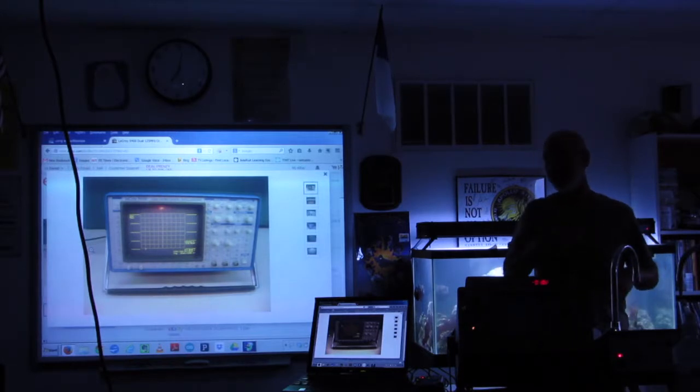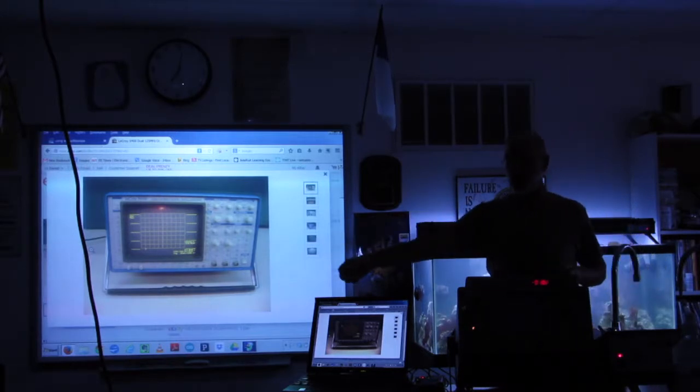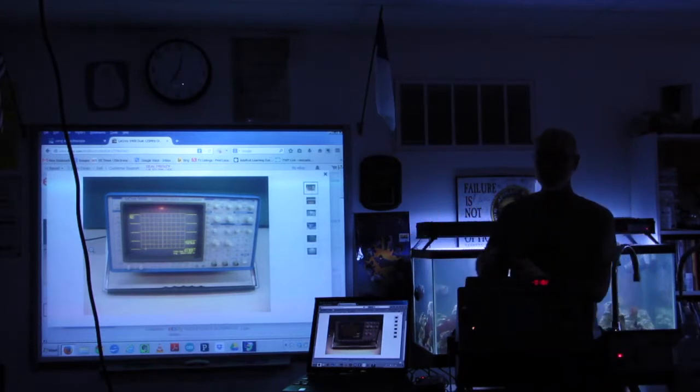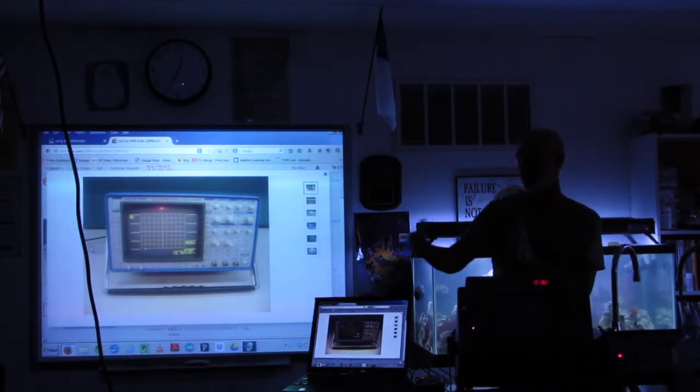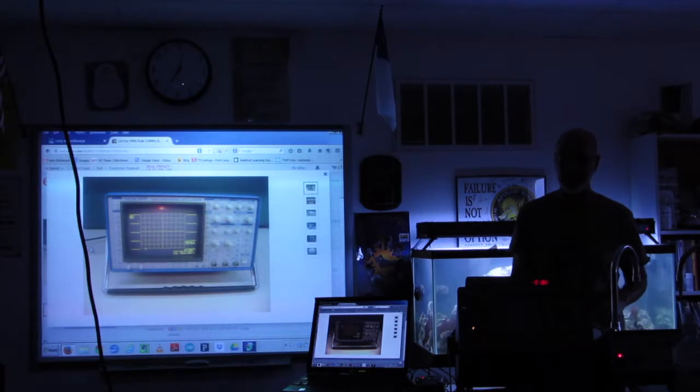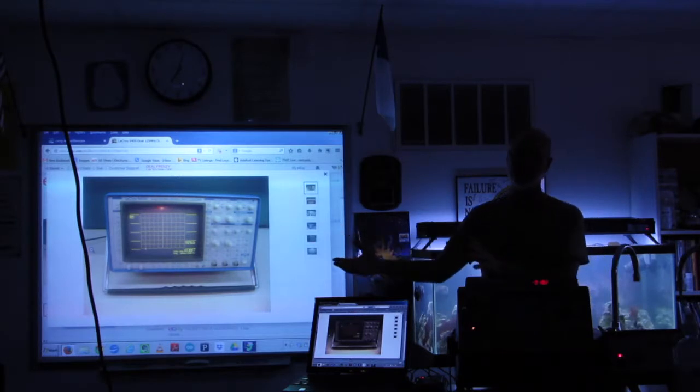I mean, it fills up fast enough, but because it's so long, it may be a while before you see anything on the screen. So there's a delay. And then, on slower scopes it just takes a while to process the information and get it onto the display. So there may be a few microseconds delay before it's actually displayed on the screen.